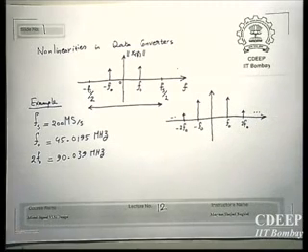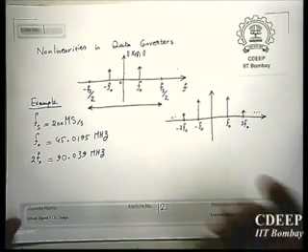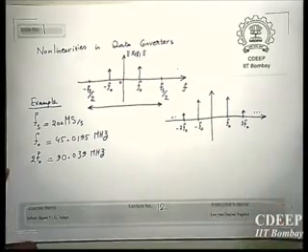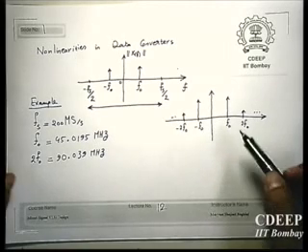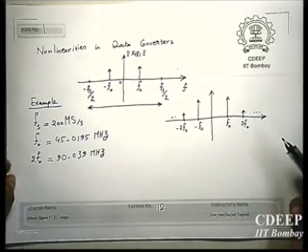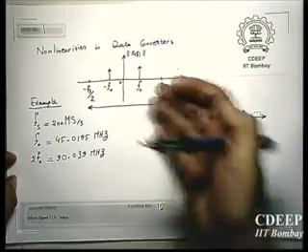Right now we consider a single frequency, so harmonics will also be single. Afterwards, because it's not perfect sampling, your spectrum will get attenuated after fs by 2.